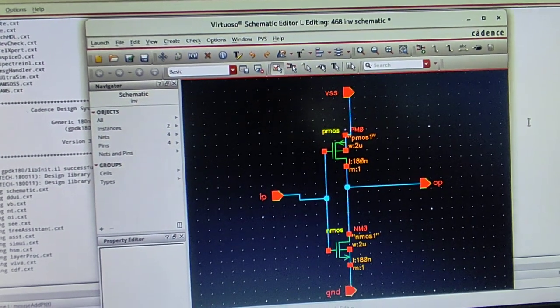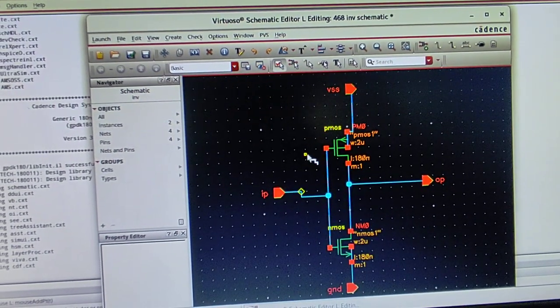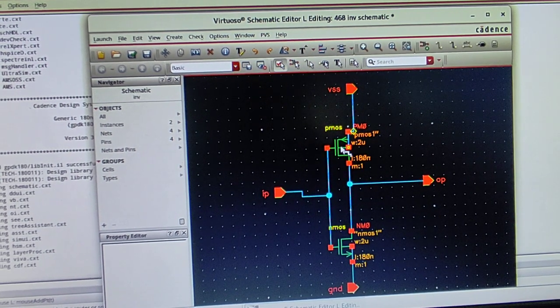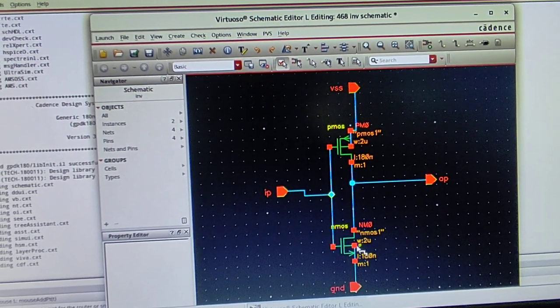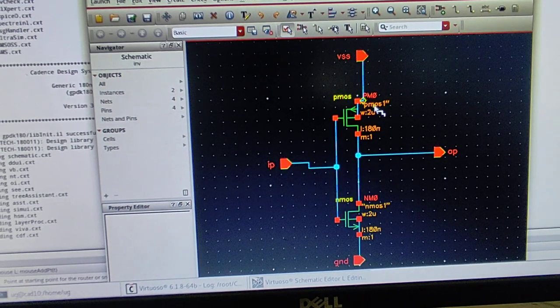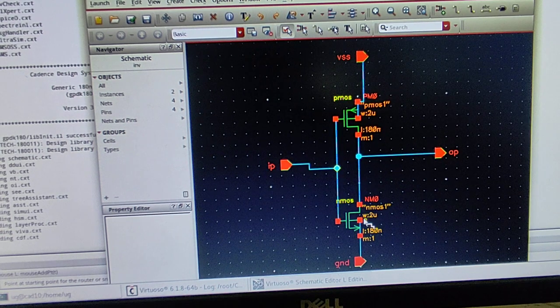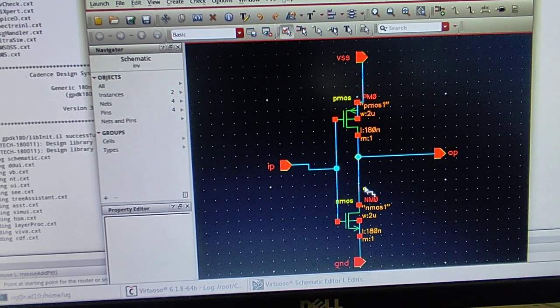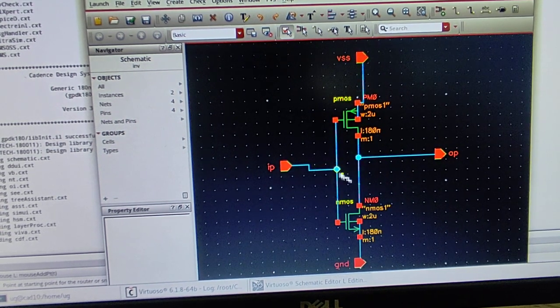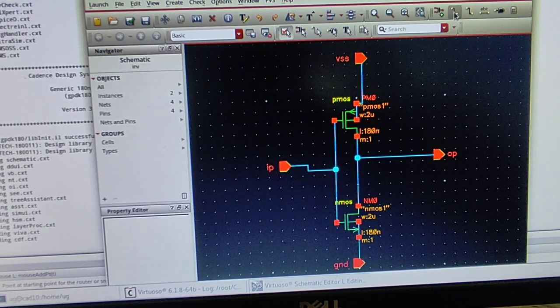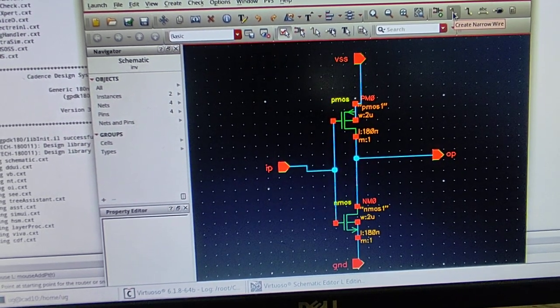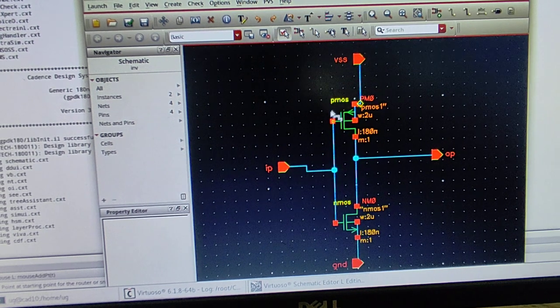So after giving the circuit connection, we have designed the schematic based on the elements we have selected, PMOS and NMOS. We are trying to design an inverter here. So we can see the points, the nodes like supply and ground connected, then input and one output that is been operated here. We are using a thin wire arrangement. Here you can see where the mouse is pointed, narrow wire arrangement, all the connections are made.